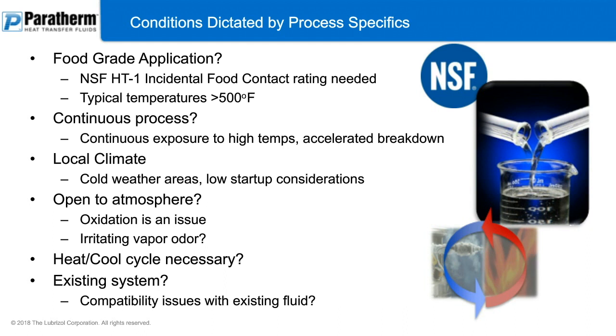Is there a heat-cool cycle necessary? Just because a fluid is capable of operating across your entire cycle doesn't mean that it's designed to go quickly from heat to cool. So you're going to want to look for something that's considered a heat-cool fluid, or discuss that with the supplier. Just because the fluid range covers your entire cycle, the fluid you choose based on that may not have the inherent capability to transition quickly, and you're going to be cycling much slower. That's a lot of downtime and could really hurt your application if you're not using a heat-cool fluid that's capable of that cycle.